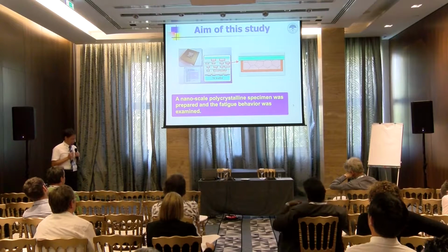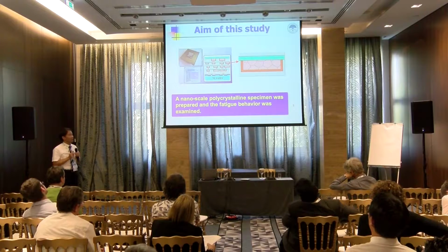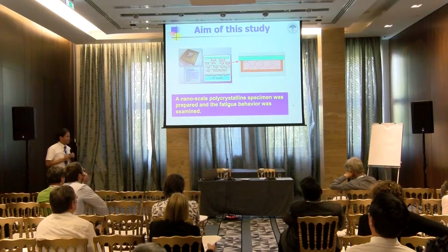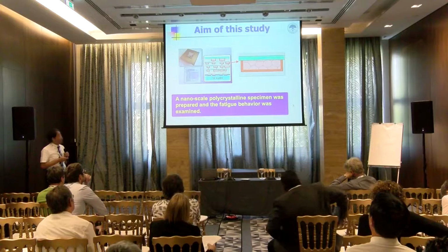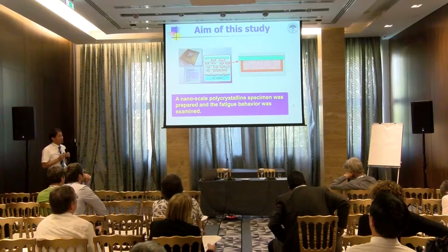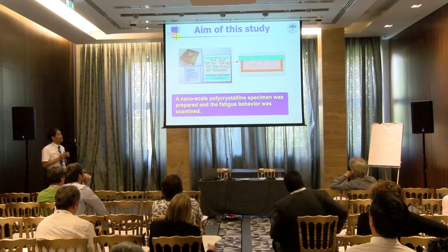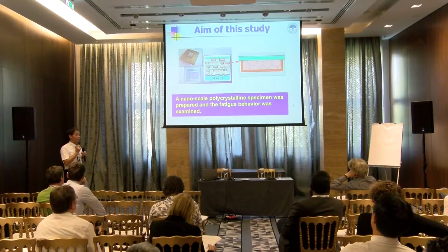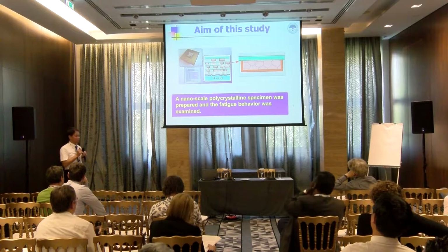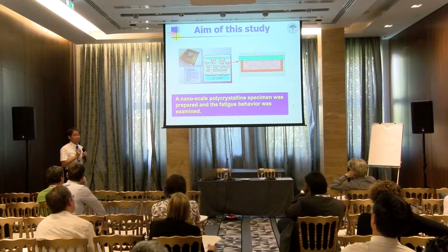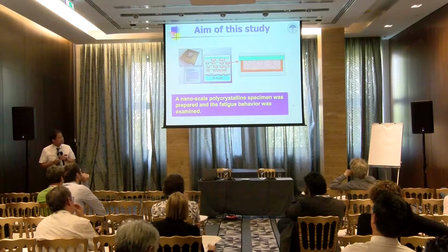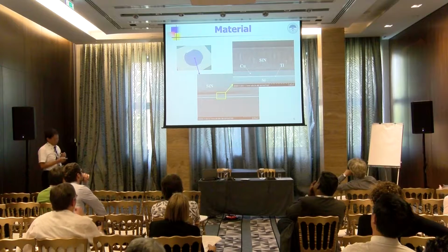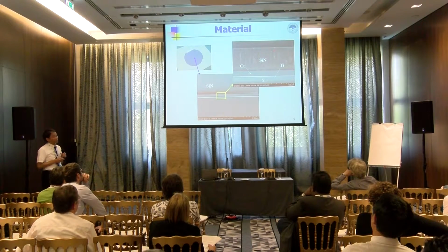Also, in this project, as a next step, we focused on the fatigue behavior of a nanoscale polycrystalline metal, which is constrained by other materials. You know, there are very small electronic components in the electric devices, for example, metal line, usually polycrystal, and they are generally constrained by other materials. So in this case, the fatigue behavior must become more complex than that of freestanding single crystal with that strong deformation constraint.